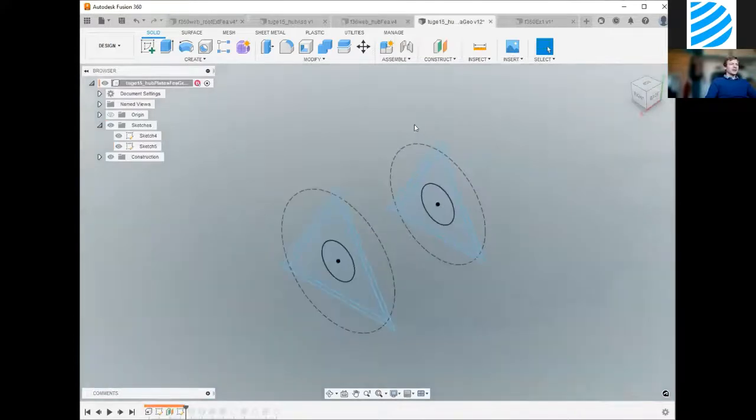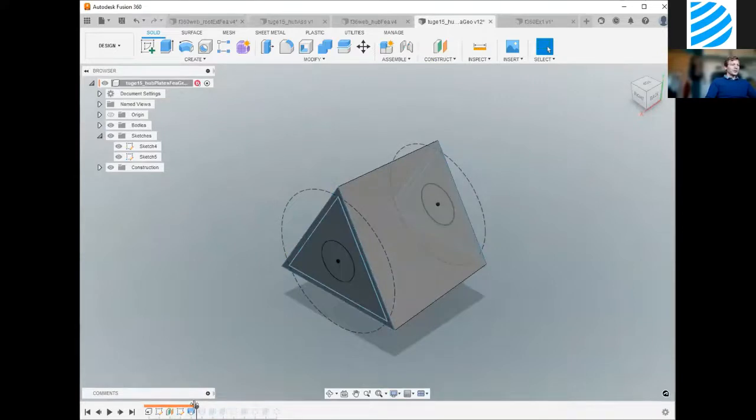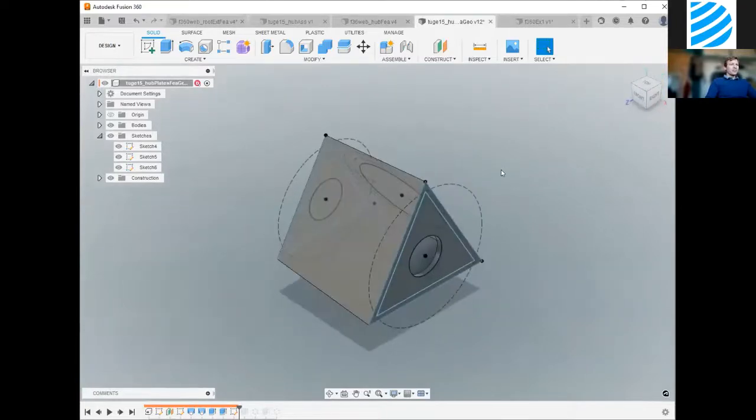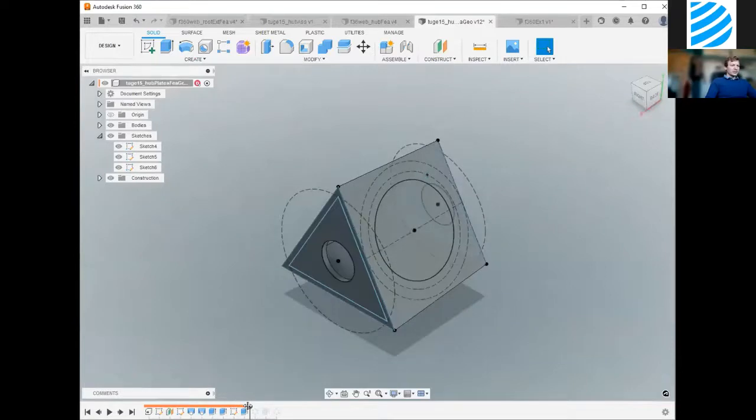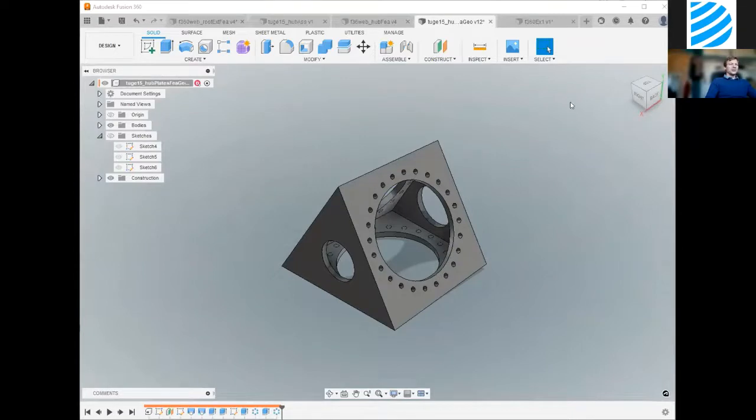And as for how I do that, you guys probably already know how to create parts, but just some simple lofting. I drew the front and back, lofted between, then I lofted out the intersection and started creating the plates on either end. Then we had where the blades are bolted, and finally the holes and some circular patterns just to finish it off. So that's just the approach that I take sometimes.